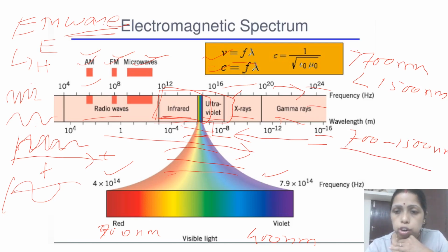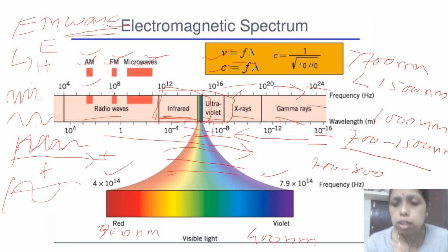Sorry, 700 to 800, or 900, nanometer are for short range communications. Above 1000 nanometer, 1000 to 1500 nanometer, these wavelengths are used for long distance communication. And below 1000, if you want to use 700, 800, 900 nanometer, these are used for short distance communication.